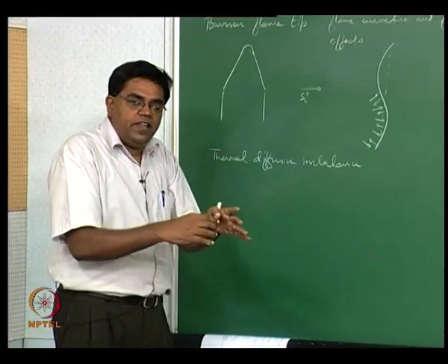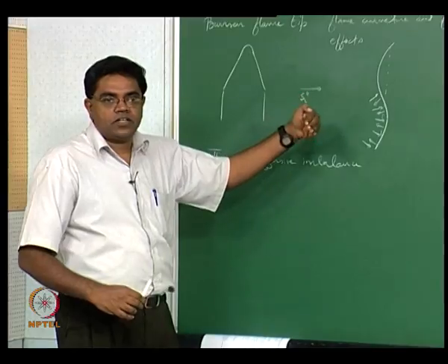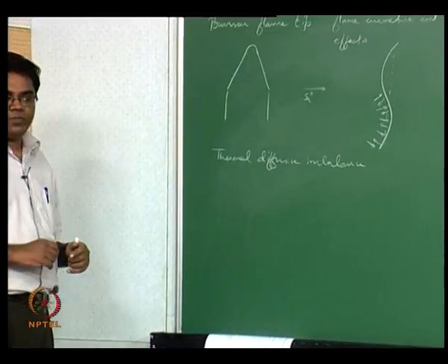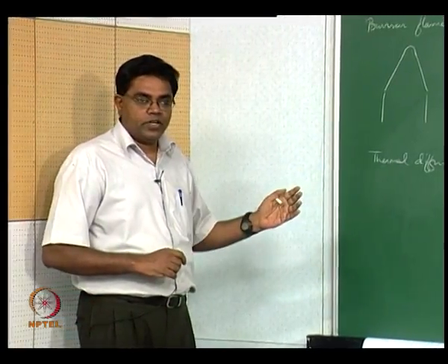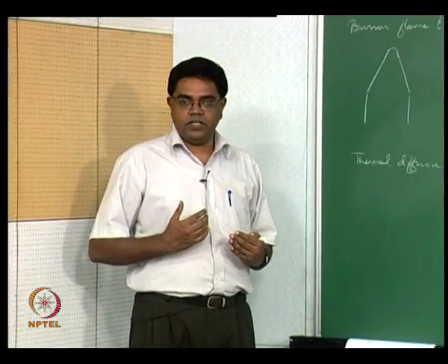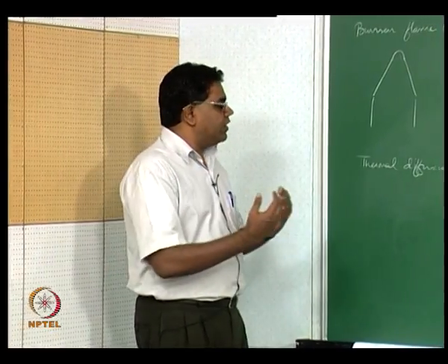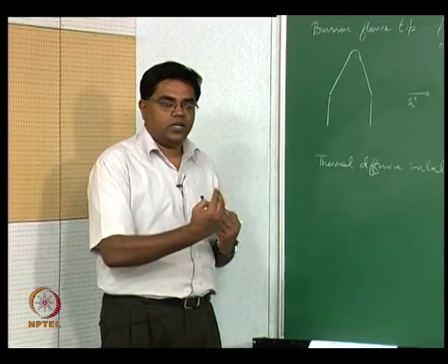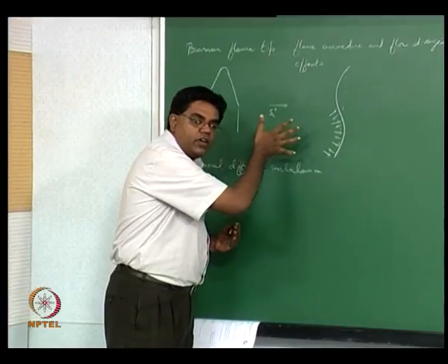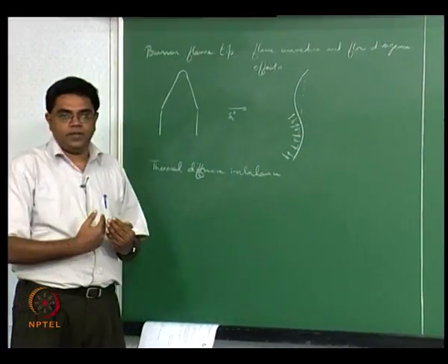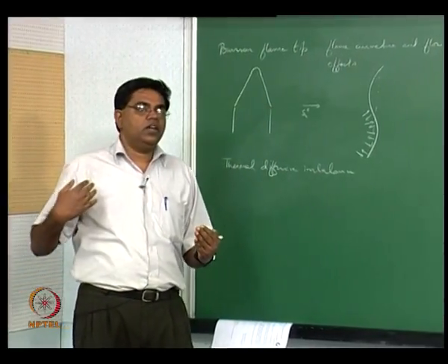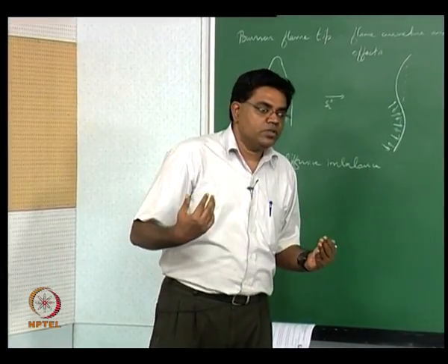That means the flame is running out of the diffusion reactant more than in the case of a planar flame if you have a concave curvature relative to the upstream. So this has a tendency to decrease the flame speed. So you now have a possible balance between these two effects that will tell you whether the curvature is going to stay, grow or decay. When you now have to think about a balance between heat conduction and species diffusion, what comes to our minds?